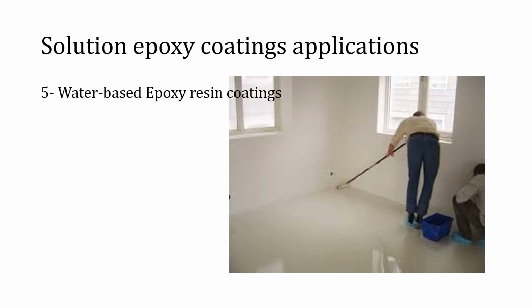For can coatings, higher molecular weight epoxy resins, for example, with molecular weight of 15,000 to 20,000, which have been initially dissolved in a solvent and then dispersed in water, are employed. These systems can be cured with either melamine or urea formaldehyde resins. The baked films have to be resistant to pasteurization conditions and comparably flexible, conditions which are required for beer cans.